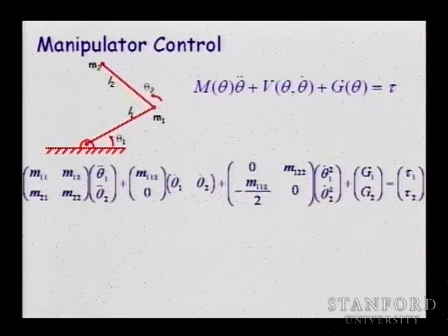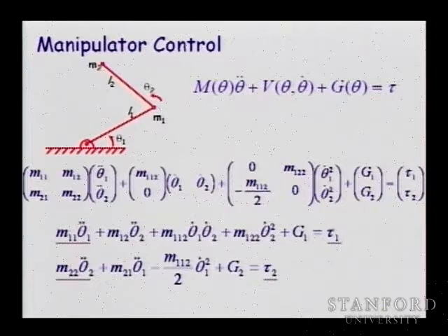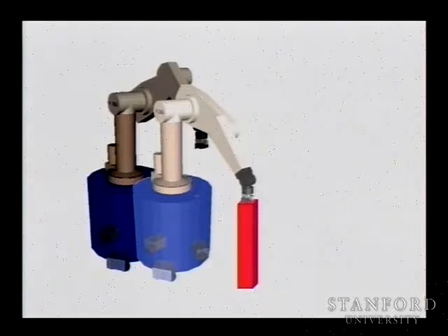You can see that the equation of motion for 2 degrees of freedom comes to be sort of 2 equations involving not only the acceleration of the joint, but the acceleration of the second joint, the velocities, centrifugal and Coriolis forces, and gravity forces. All of these will have a dynamic effect and create disturbances on the behavior, but we will analyze a structure that would allow us to design torque 1 and torque 2, the torques applied to the motor, to create the behavior that is going to allow us to compensate for those effects.